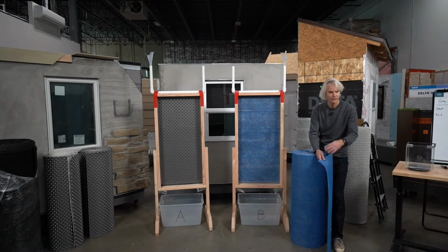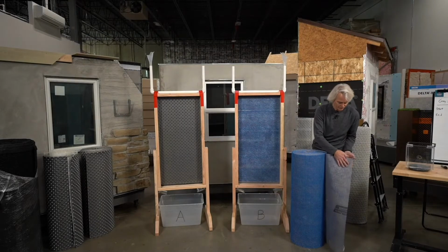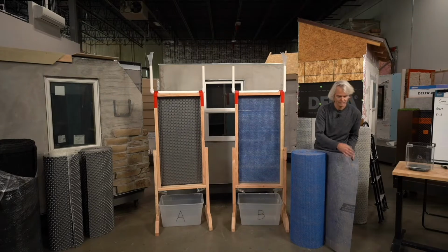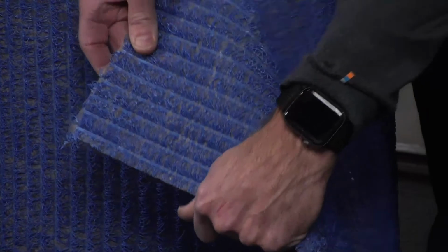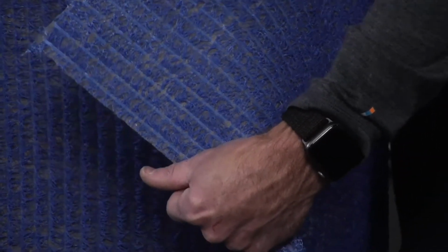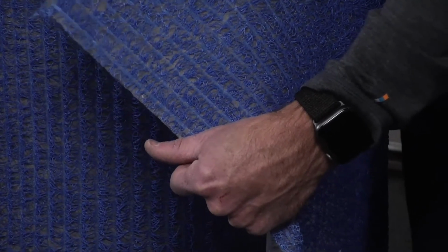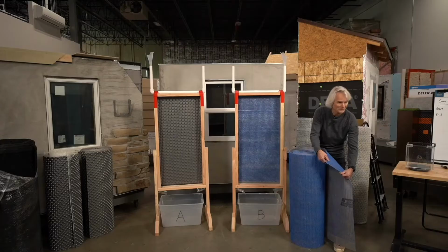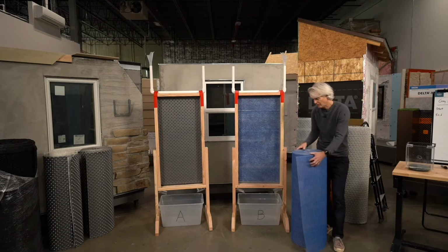And it's an entangled woven nylon mat as a rain screen product with a facer on the front that is for a layer to catch any mortar. So you'd put your lath directly atop this, your scratch coats, etc. And so here we've got this entangled mat that you can see, and you can see it's an interwoven fiber, though it's got very good compressive strength. This product is about 1/4 of an inch thick, so probably right around 6 or 7 millimeters if I'm going to put that into metric mode.